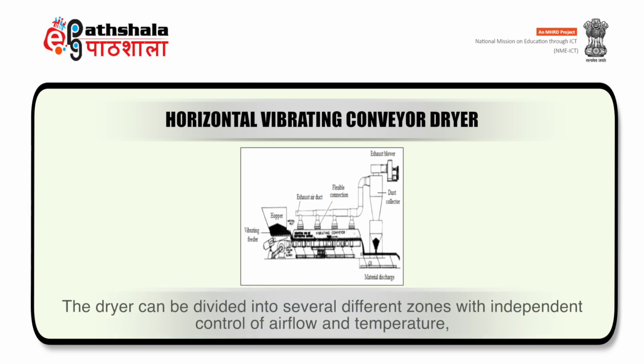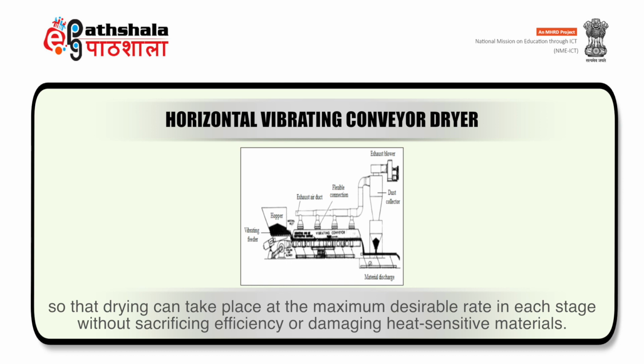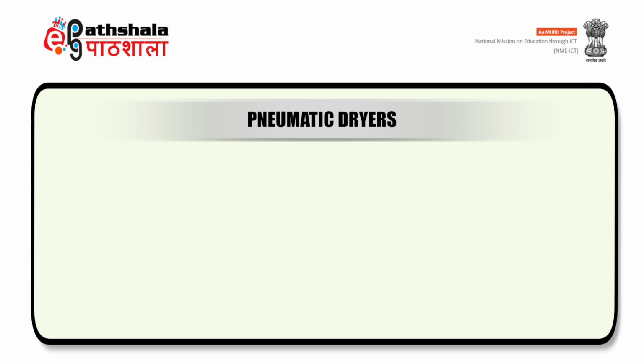The dryer can be divided into several different zones with independent control of airflow and temperature, so that drying can take place at the maximum desirable rate in each stage without sacrificing efficiency or damaging heat sensitive materials. Now coming to pneumatic dryers.